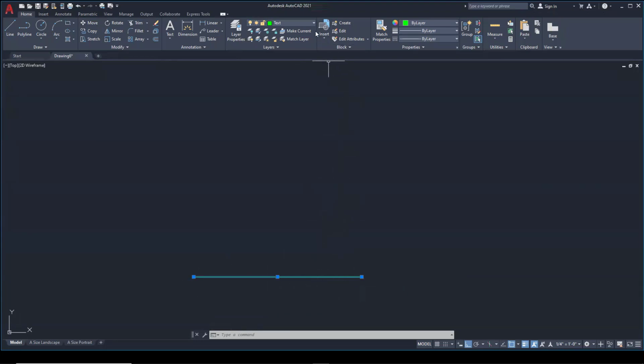And then I just go up to my layers here and say, put it on walls. And you'll notice just as I hover over it, notice how it's changing color. That corresponds with the layer that I happen to be scrolling down with up on this drop down here. So I'll just go on to walls and click on that. And now I'm on the walls layer.